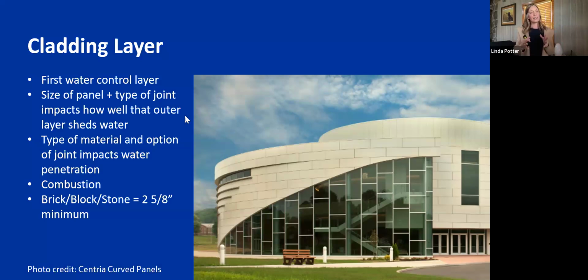However, the concept of your Rainscreen wall is you anticipate that water will get back behind that cladding, just like you would in a brick wall, from however it's going to get in there. There's several different ways water finds its way in a building. That you've got a way for it to get out and stay dry and not cause problems back behind that cladding that you can't see.